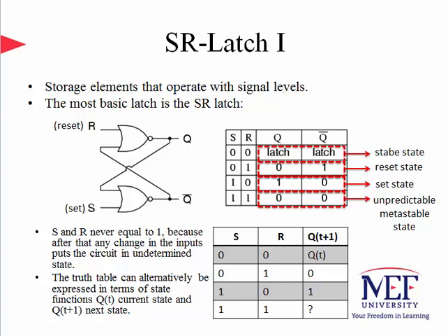If you follow the wires and think about binary signals flowing in and out of the circuit, you will see that state 00 is the state that the SR-Latch uses to store bits. When the S input is set to 1, then the latch is set, in which case the Q output becomes 1 and Q prime becomes 0. When the S input is switched back to 0, the outputs Q and Q prime stay the same, and hence the latch is set. A bit 1 is stored, until one of the inputs is changed to 1 again.